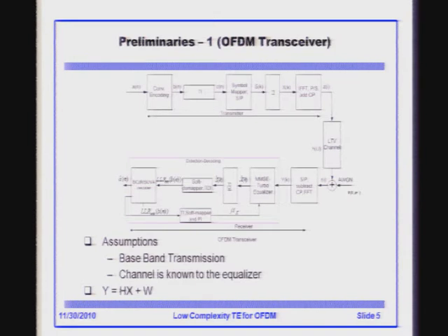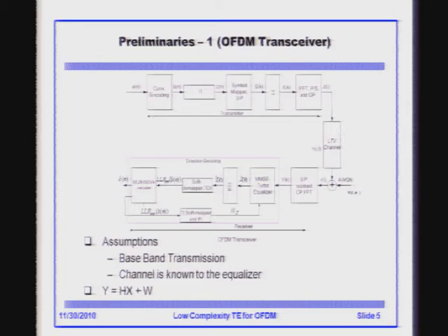Whatever is coming out of the BCJR decoder will again be log likelihood ratios, soft information otherwise, and that is passed on to a soft mapper, which will convert it into a soft mean and variance, which is another input to your MMSE turbo equalizer. And this is the iterative loop. That is how it iterates between the equalizer and the decoder.